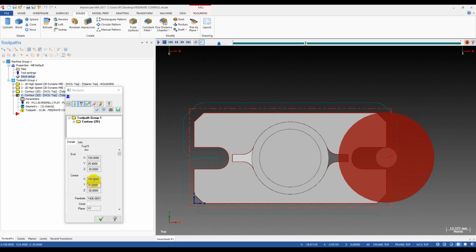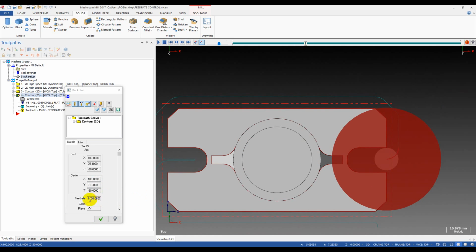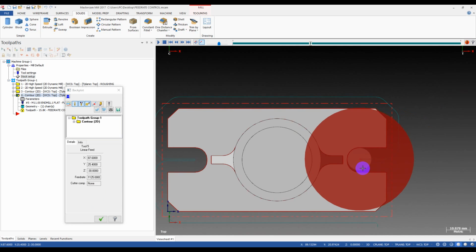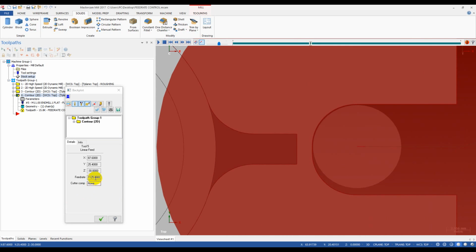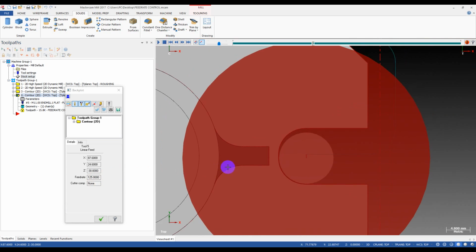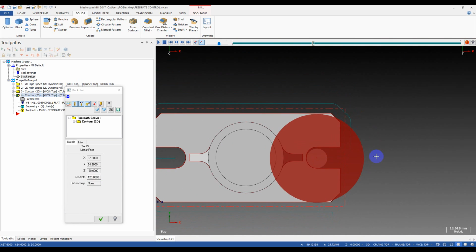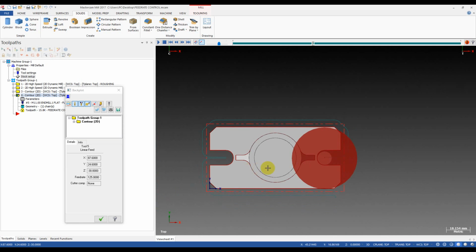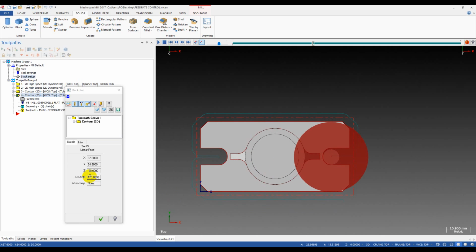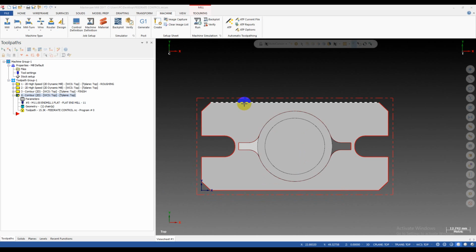And you can see the feed rate changes based on the tool position. Yes, when it goes to the corner here, the feed rate reduces a lot, and you can control how the feed rate changes by going to the machine dynamic parameter and modifying some parameters. Okay, and now we're going to move to the machine dynamic parameter to see how we can control the feed rate.